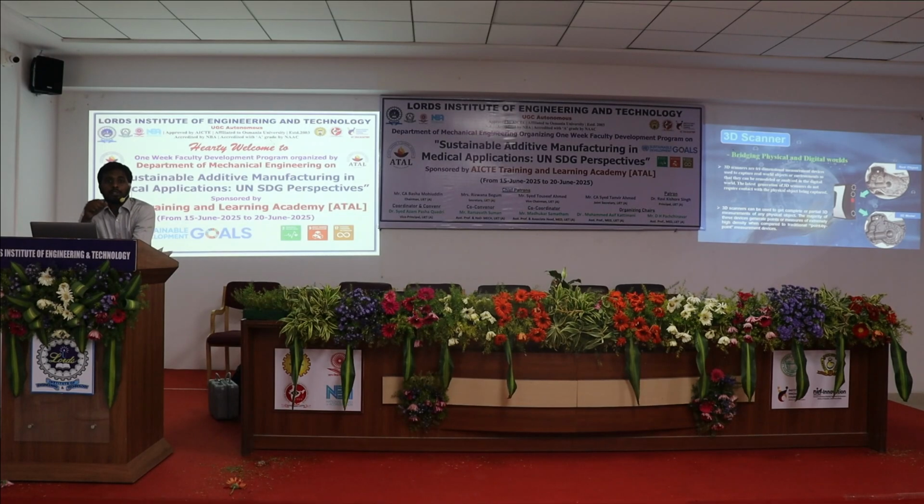These kinds of scanners do not contact the component and scan it with good accuracy, like 40 microns, 20 microns. In some scanners we get 5 microns accuracy also, and we get point cloud data and then convert it into mesh data.